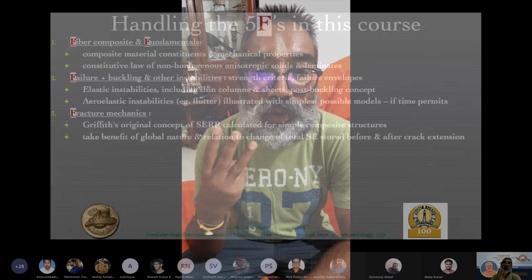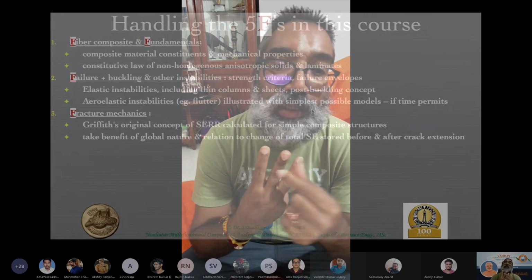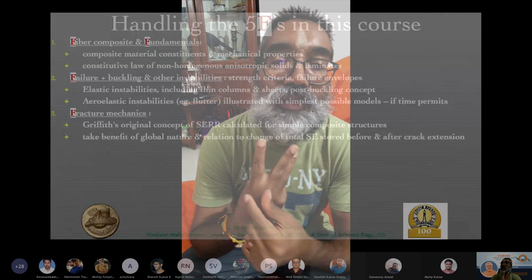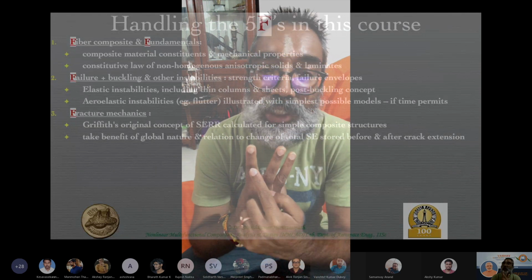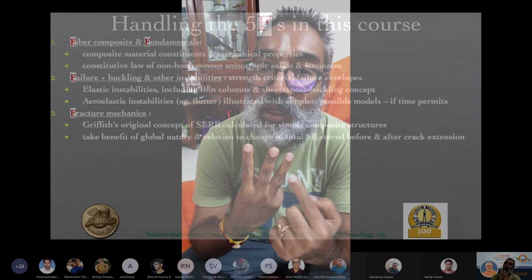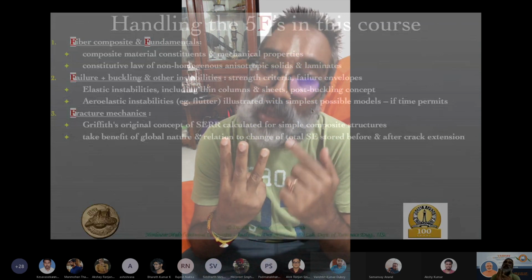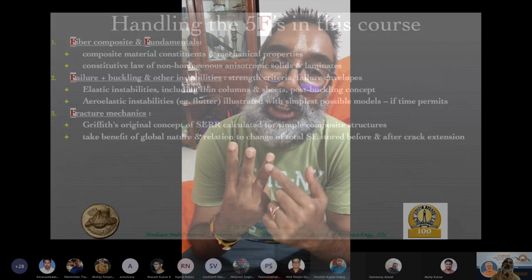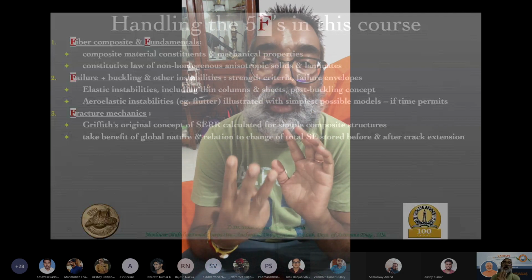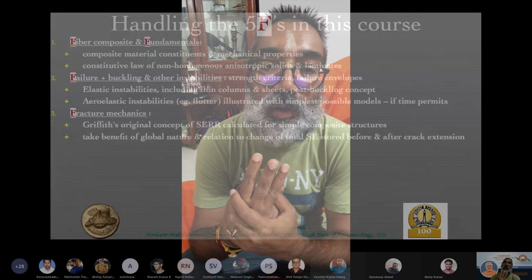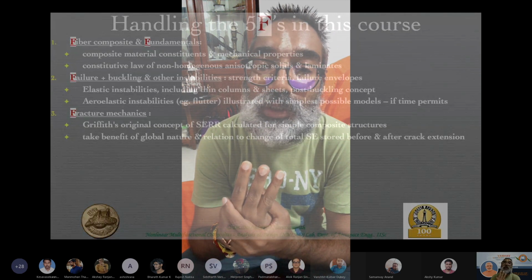So these are three totally different behaviors. One is linear, non-linear behavior, the other is isotropic, anisotropic behavior, and the other is homogeneous, non-homogeneous behavior. Homogeneous, non-homogeneous is basically from point to point differences. This is at a point in different directions. And this is at a point in a given direction, but changing with increasing strain. So these are three mutually independent types of behaviors that you can have either in a composite or even in metals.